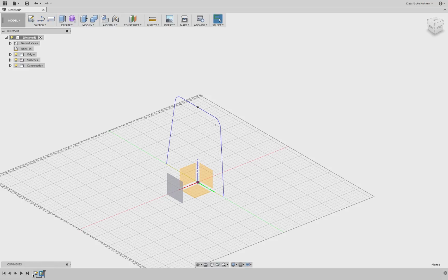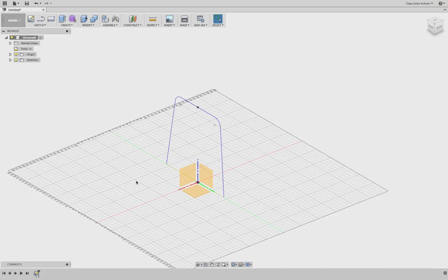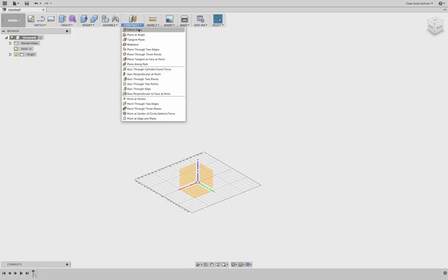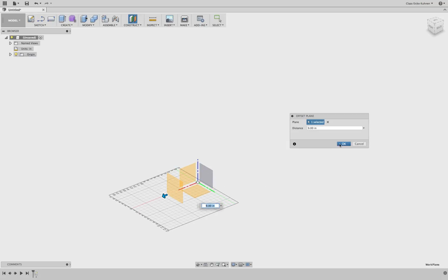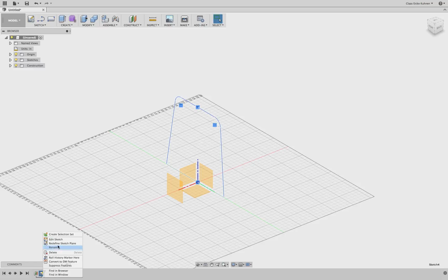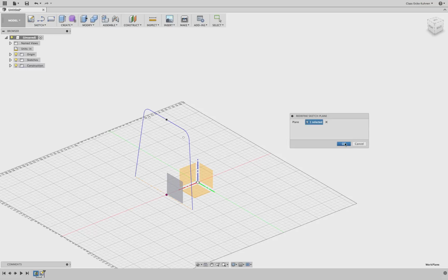So we have to either drag this one to the left, so in front of it, or we can also put the time marker in front of the sketch because, technically speaking, we forgot this step. So we do this now in time. Okay. And then we go back in time, right mouse button click, redefine sketch, select this one, and it moves.